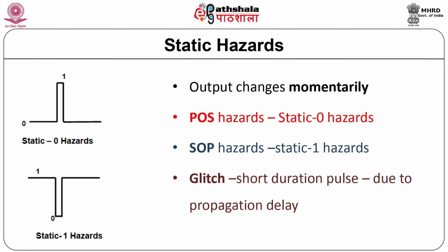A glitch is an undesired transition that occurs before the signal settles to its intended value. In other terms, glitch is an electric pulse of short duration that is usually the result of fault or design error in a digital circuit. The glitches are generated because of the propagation delays of the logic gates.